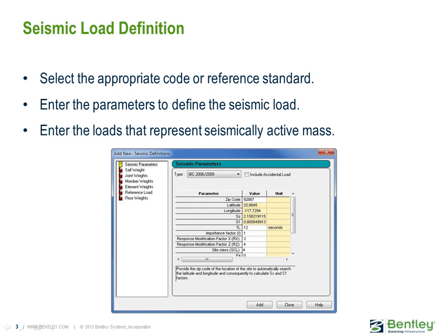Staad Pro has the ability to generate loads to perform a seismic equivalent lateral force analysis according to a number of different codes and reference standards. In Staad Pro, load definitions are used to add supplemental information before the load can then be applied to the model. When it's applied to the model, it is actually applied in the form of load items and load cases, which we'll get to in the next video.